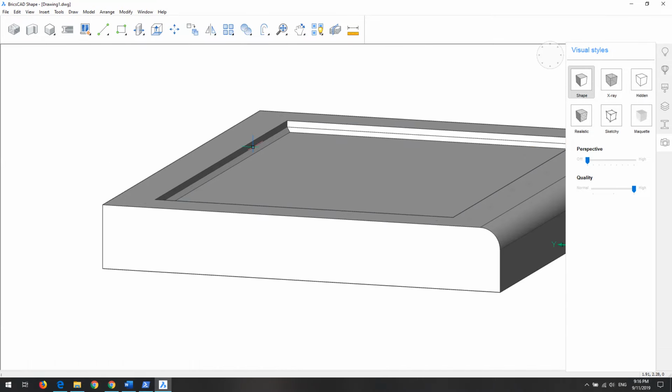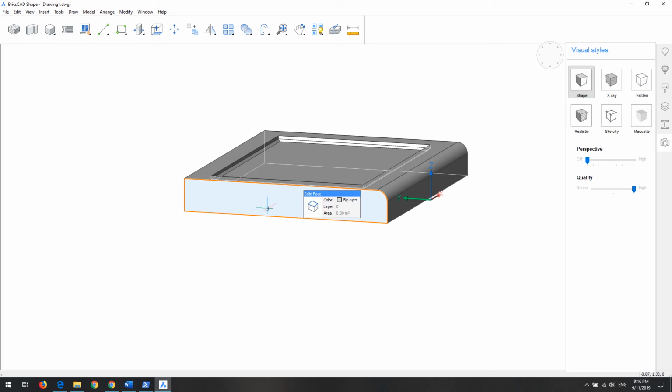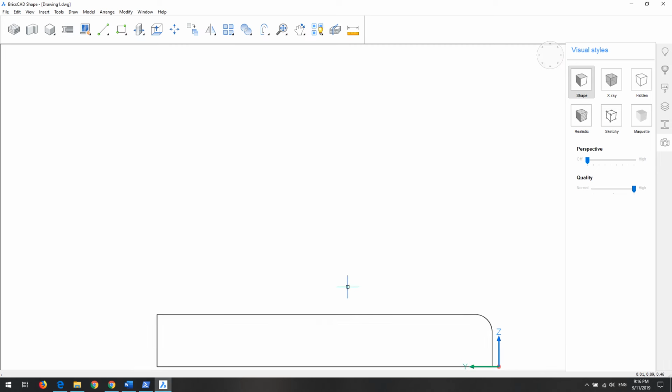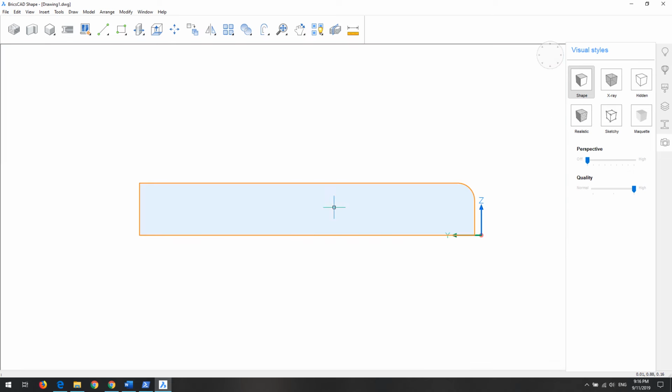Now that we have that, suppose we want to extrude a cylinder on this face. First let's look from this side view, the left view, and we set it to orthographic view so that it's perfectly aligned. Then we can use the circle tool here and just click on that, and it automatically gives you guidelines. Like I want to create a circle in the center of this fillet, let's say, and I just drag and define it, or just type it in maybe.